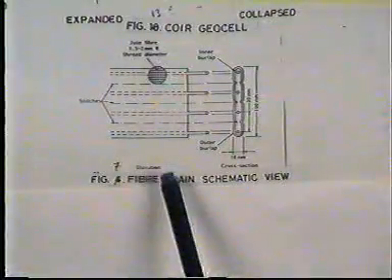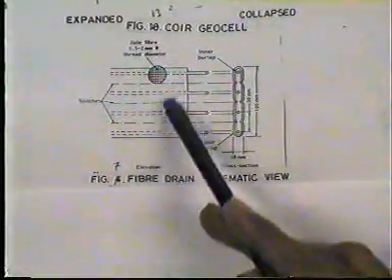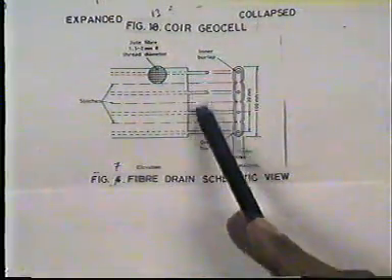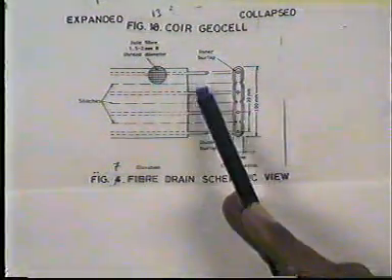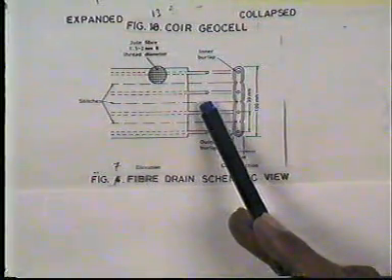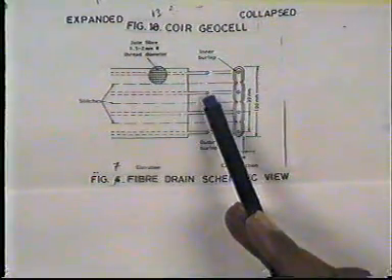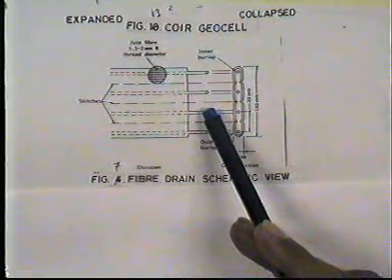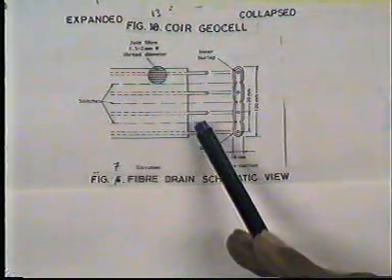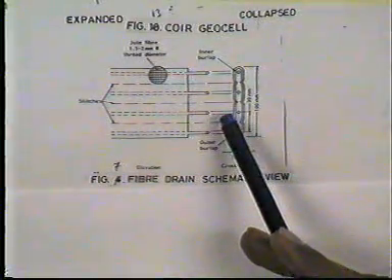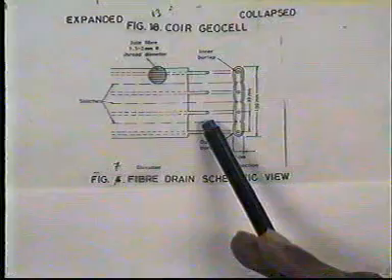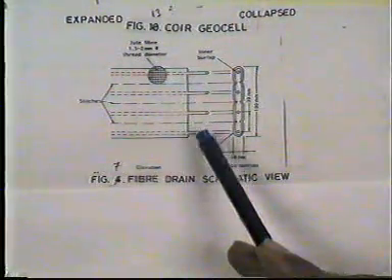Here, a type of flexible jute prefabricated drain known as fiber drain, made out of jute fabric, suitable for consolidation of soft compressible soil, has been developed and field tested.